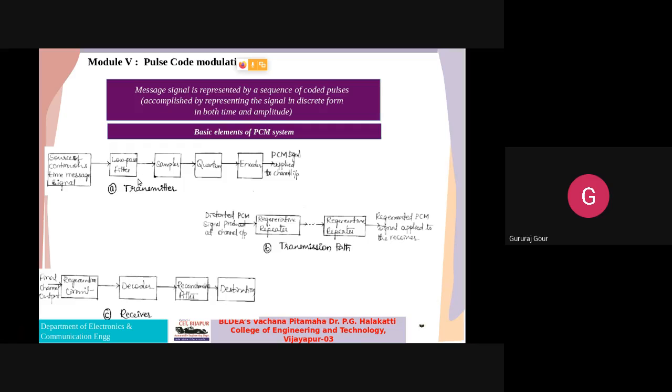One, it is avoiding any high frequency noise content. Second, it is taking care of the aliasing effect on the part of the signals to be transmitted over the common path or transmission path. Then that signal is applied as input to the sampler, or sampling process.